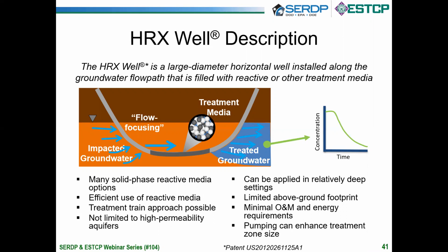And there are a number of, I think, advantages and distinctions to this technology. Of course, there are many solid phase reactive media that are currently available. And I think maybe something that differs from let's say a conventional trench-based PRB is that the use of the reactive media is very efficient. You're not wasting that. All that water gets focused and then is pushed through the reactive media. And what that means is that the amount of reactive media that's used is quite small, and therefore allows maybe more expensive media or designer media than you would normally consider for a conventional trench-based PRB.